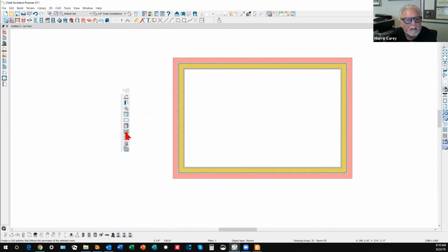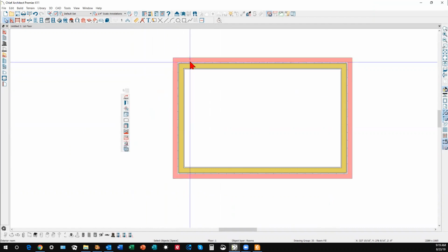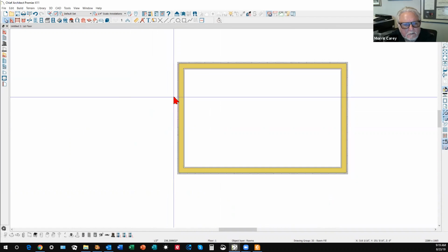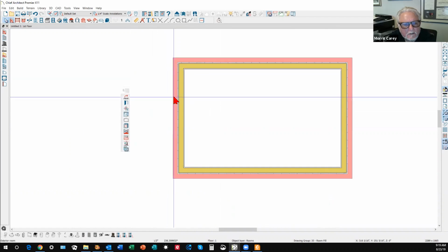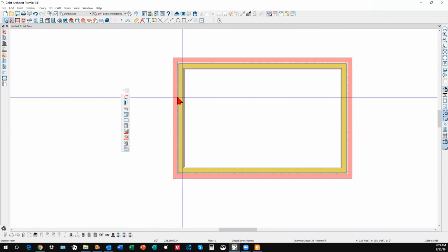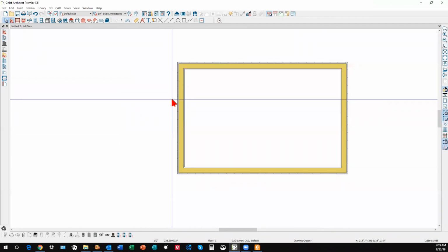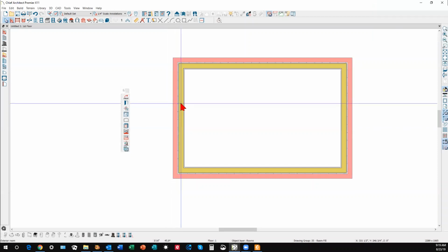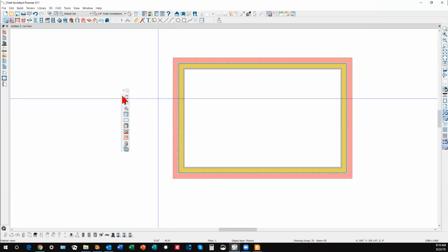How'd you do that? Left click outside the wall, and then hit the tab key. You have to have your cursor the right distance from the edge of the wall for that to happen. And I'm just left clicking, without touching the wall. Okay. Good.